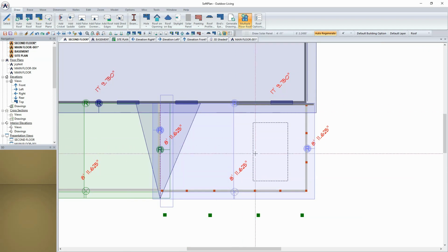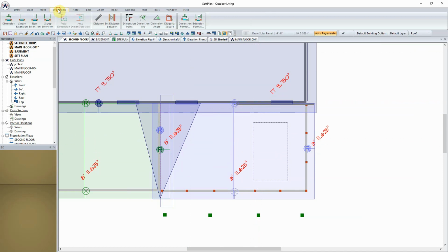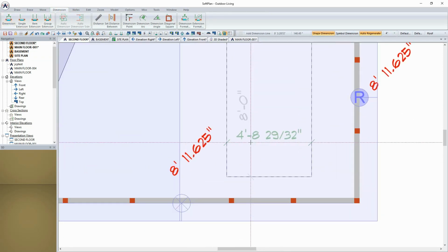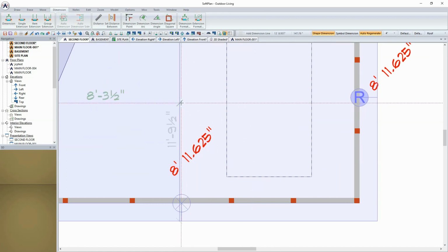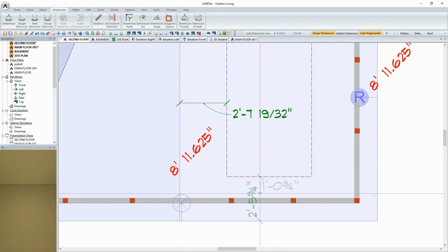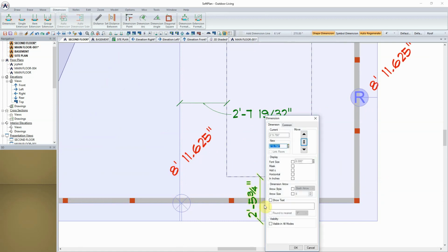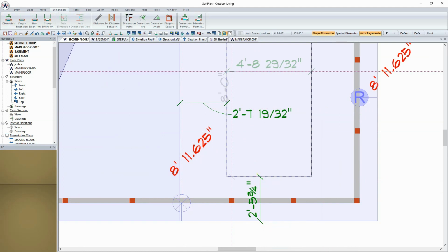A review inside the 3D shaded model will show us what we have. In the event that you wanted to dimension this into place, you at that time could then just simply take your cursor up to the dimension menu, select dimension from the ribbon bar, and then position your cursor in a placement point on the roof whereby you can click on the ridge line and run the cursor from left to right, and it will put the dimension in place. Likewise, you could do the vertical.